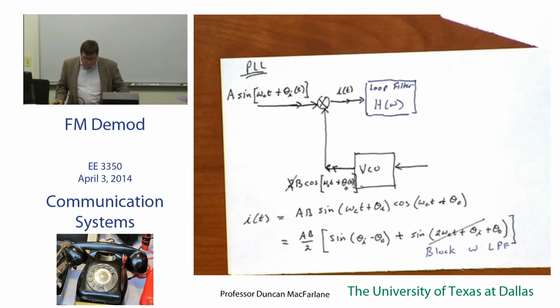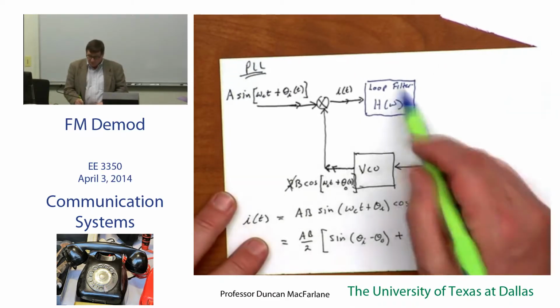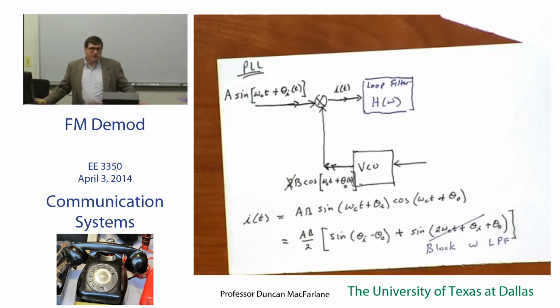Now, in a digital implementation, this loop filter is going to be realized with a high-order feed-forward filter, and you can do very, very well. You can adjust phases independently of magnitudes, and you can do that with great precision at the cost of the sampling rate, the speed of the whole system. Okay?